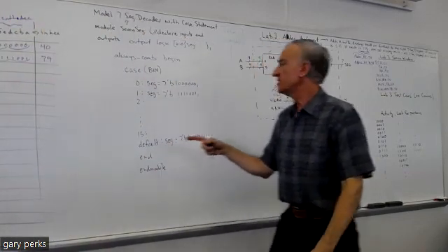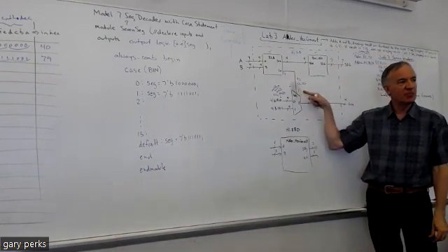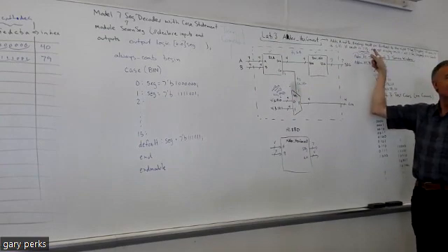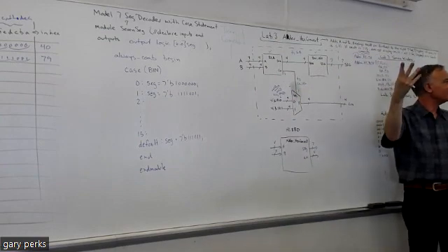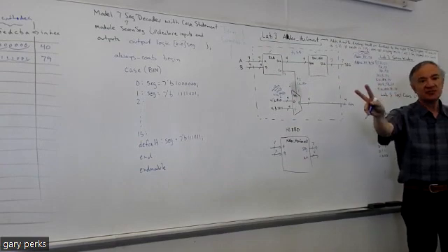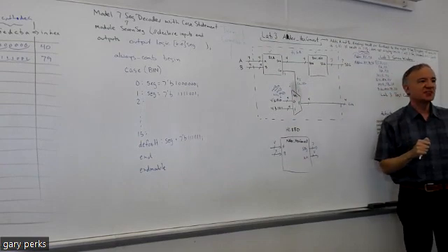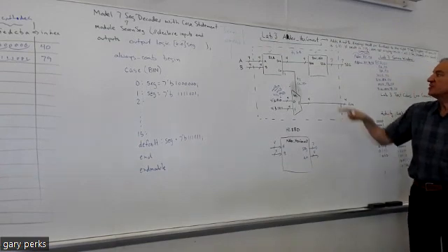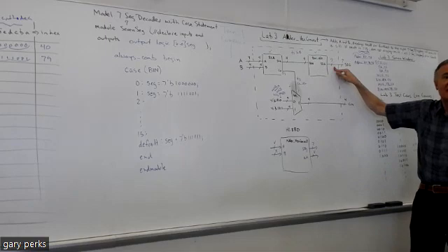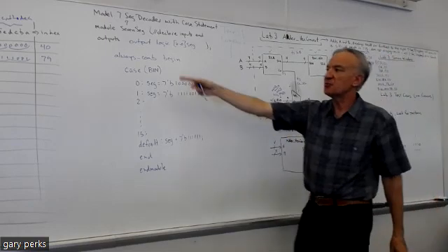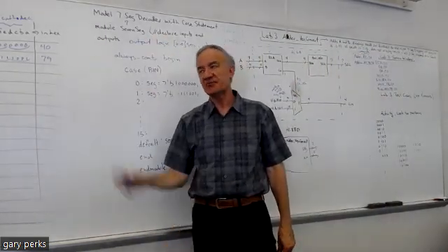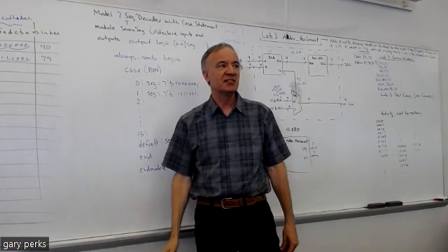So do you see how using the carry as a select to the mux accomplishes this, where we blank the displays if the result is greater than 15, but we can show a display if the result's 15 or less? And if the result is 15 or less, that's when the seg output matters, right? Because depending on what our seg bits are, that's going to determine what's displayed on that furthest to the right 7-segment display.